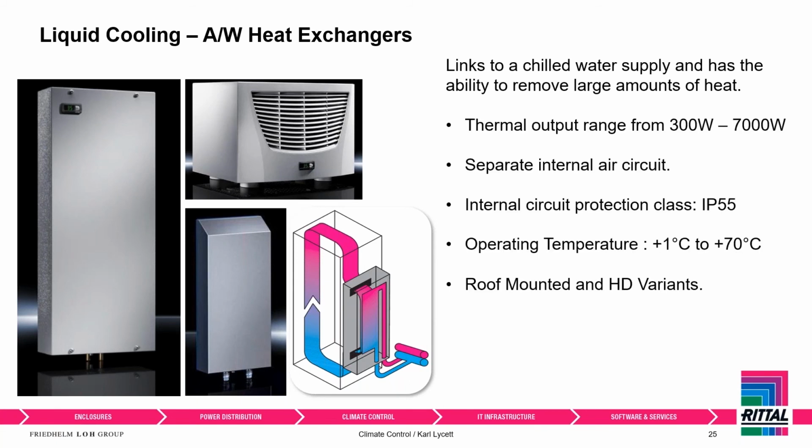So we offer very small air to water heat exchangers, 300 watts up to 7 kilowatts. So again, they can be banked together and daisy chained. So you can start to do some serious cooling if you really want to. Still, that separate internal air circuit, as you can see, it's a very sealed box. You're not getting debris getting inside your enclosure. It's IP55. The operating temperature is, again, above freezing, because when you start getting below freezing, that's where it goes into more specialized equipment, more like refrigeration equipment. And then it can work, though, up to +70.